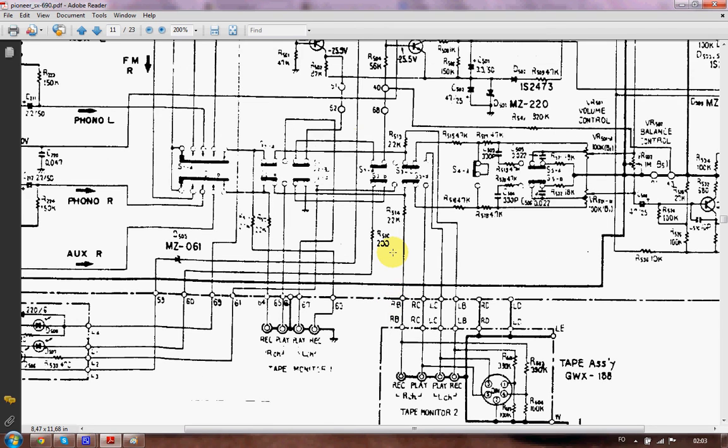And instead of doing what I did, instead of thinking about the most complex part of your circuit, how could I ever repair this? Begin where it's easiest. Have a logical approach. Does it get fed? Do we have the expected inputs?